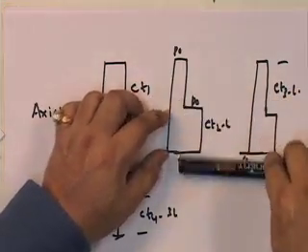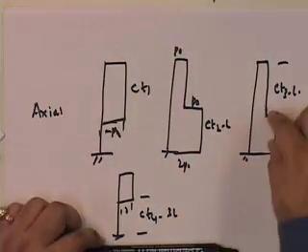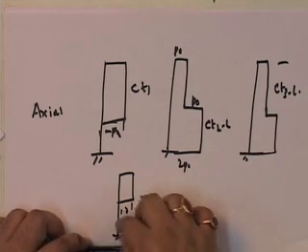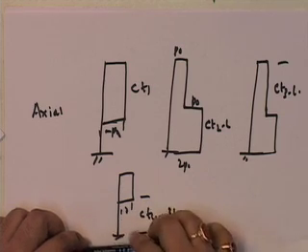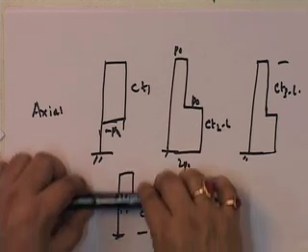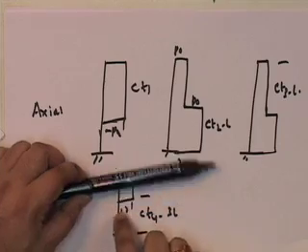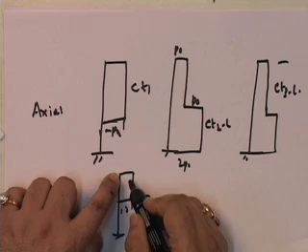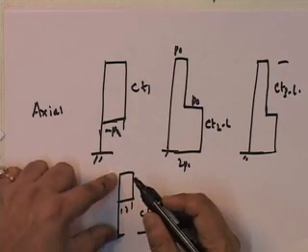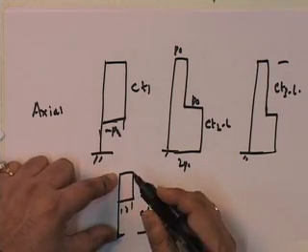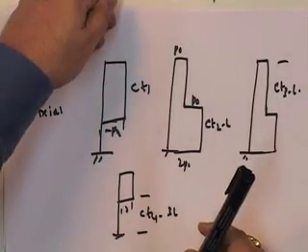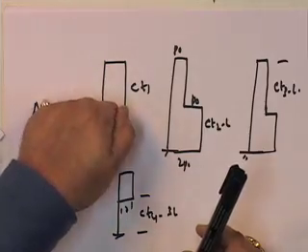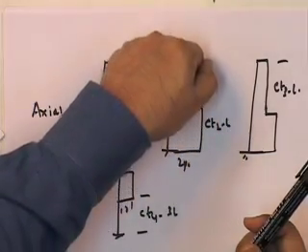Then it comes over here, and these two waves become destructive: P naught and minus P naught. So this wave goes back, and this becomes the unstressed part. So at 4L you have an unstressed situation. So suddenly applied, it's unstressed, then the wave starts traveling, constructive, so it starts going back as 2P naught.